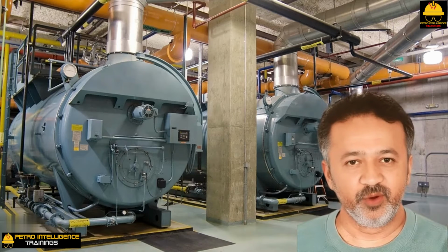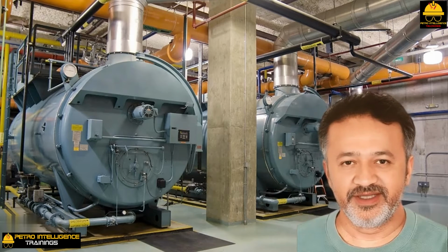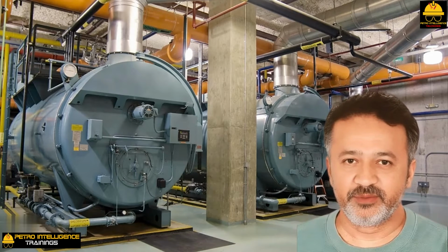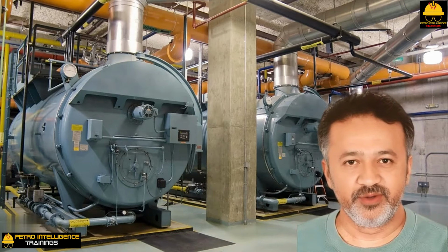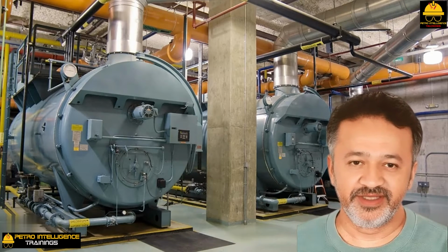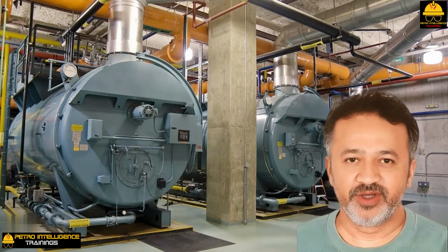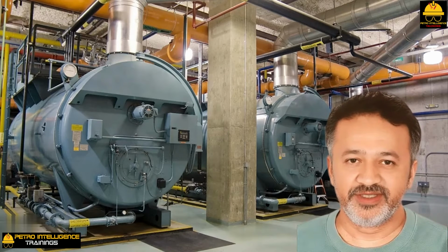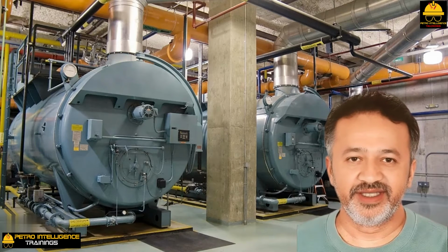A substantial portion of the steam is used for process steam stripping, purging vessels, instrument connections, flare dispersal, and other non-recoverable uses. Thus, the 70% rate is really rather good. On the other hand, 30% condensate recovery as a percentage of the steam generation rate is rather bad and represents sloppy operations and bad condensate recovery design practices.